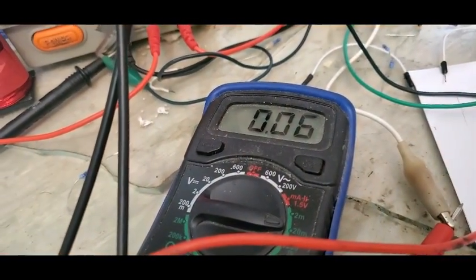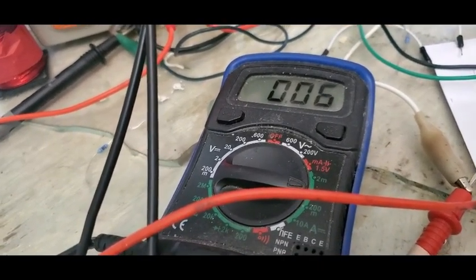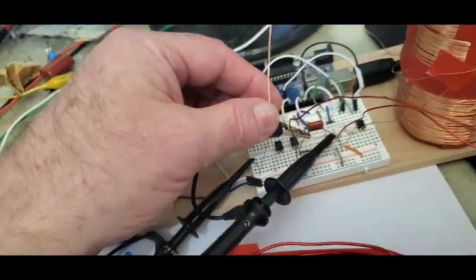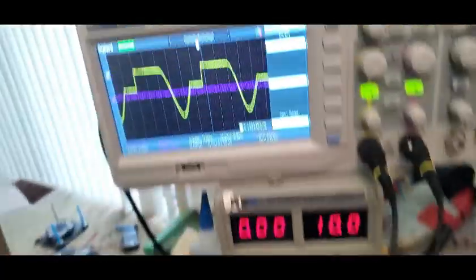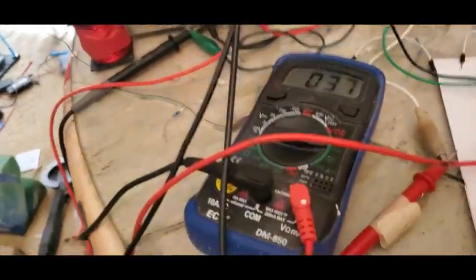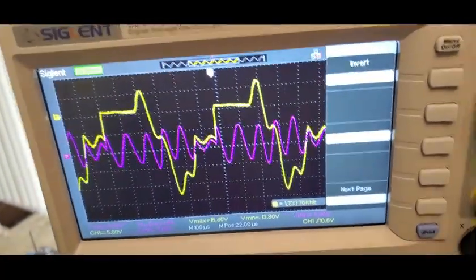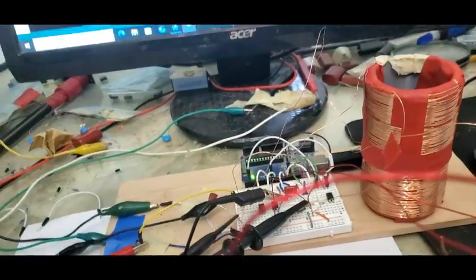This has gone way down. I don't know exactly why. I'm sure it's had enough chance to discharge with 220 microseconds, but we've only got one wire on the secondary, so let's try and hook that up as 2 wires. Okay, that way didn't work, and the amp draw is way high, even though you wouldn't expect it to be. Let's switch those around. Well, it looks kind of like what we had before, except for now instead of drawing 0.06, we're drawing 0.55. So, 1 wire on both that and the secondary is the way to go.